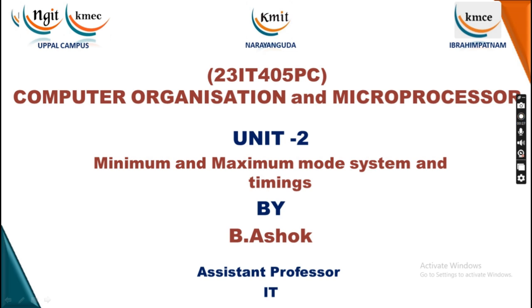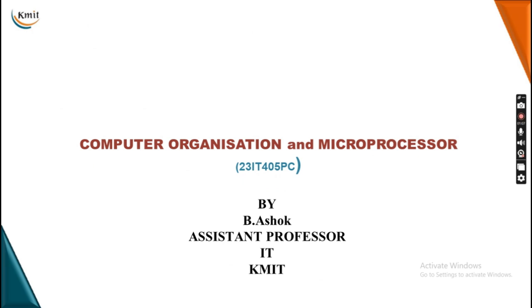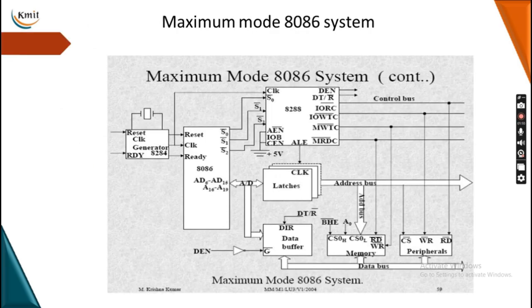As you all know, how this microprocessor will be operated in minimum as well as maximum mode depends on one pin, which is MN/MX bar. If MN/MX bar is equal to 1, then it will be operated in minimum mode, and if MN/MX bar is equal to 0, then it is operated in maximum mode system.